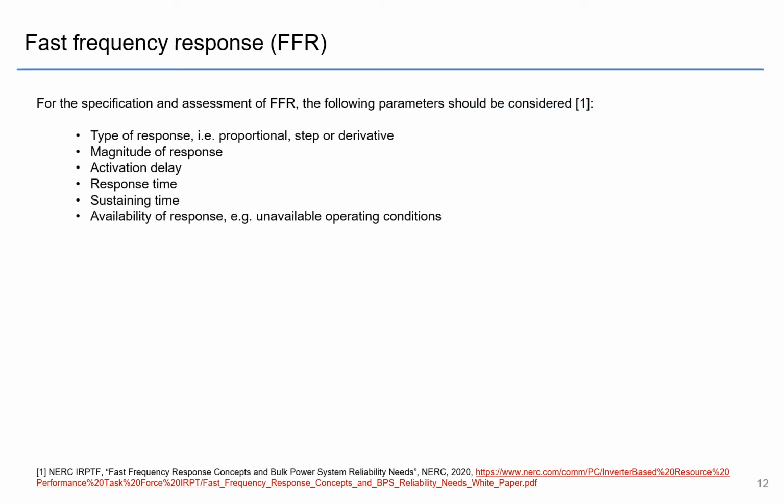For the specification, assessment and certification of FFR, the following parameters should probably be considered. The type of response that will be provided, so a proportional, step or derivative response, the magnitude of the response, the activation delay, the response time, the sustaining time, so this is how long the response can be provided, and the availability of the response, so unavailable operating conditions.